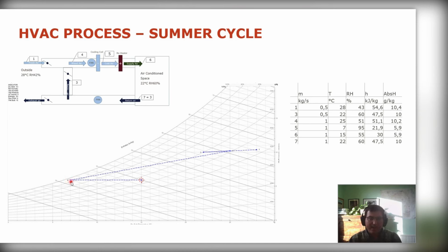It will be off by an amount that depends on the design of the coil, and there's a number of things that come into it, but let's say by about 3 to 5%. So rather than a relative humidity of 100, you can draw a curve at about 95, like that. And what we're saying is that you would cool down and then follow that curve down to whichever point you want. So that's basically what will be happening.